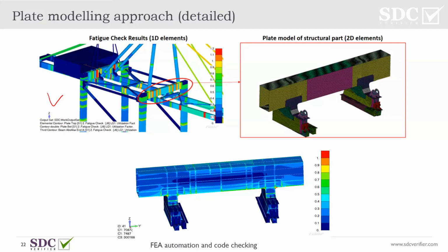In general, it does not give a good representation of the fatigue-prone areas, especially because the simplified beam element approach gives us stresses only in one direction, while complex designs involving very local plates welded together define complex notch classes to be applied there. So at the end, you receive one result per whole cross section, which of course is not enough even for easy visual inspection.